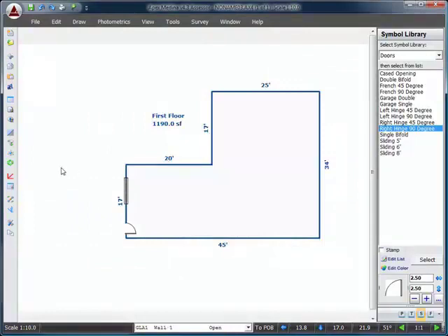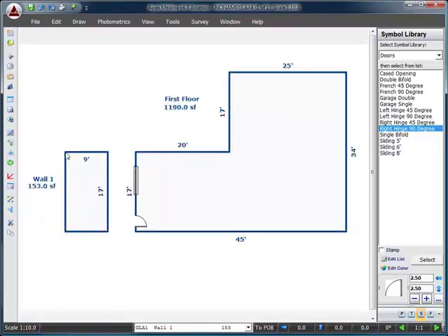Now I'm going to draw the shape by entering its dimensions, 9 by 17. Now I'll place this shape by moving it into alignment and then pressing enter to anchor it in position. I'm going to move the area name and the calculations over here to the left, and you can see that the area's calculation without any adjustments is 153 square feet. Now it's time to subtract the openings for the door and the window from this area.